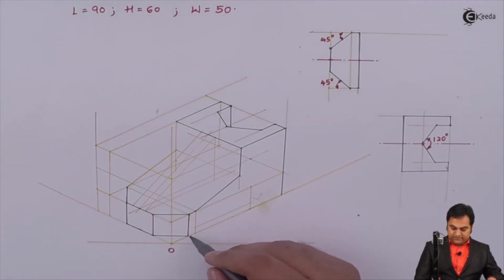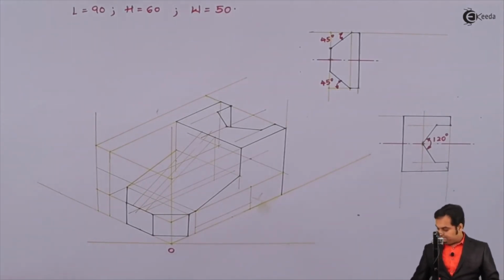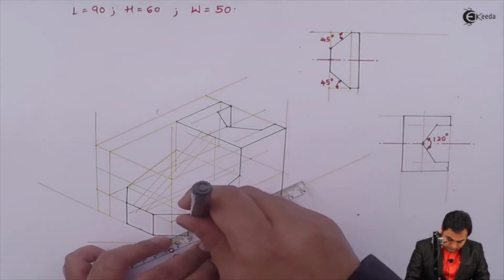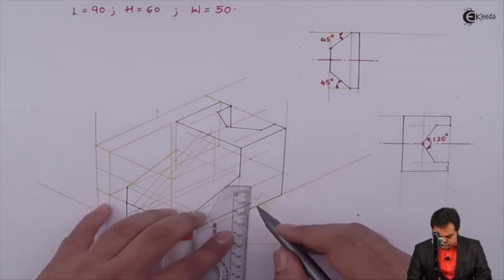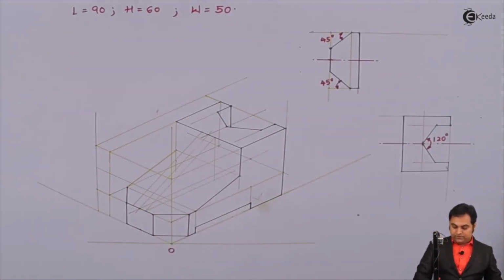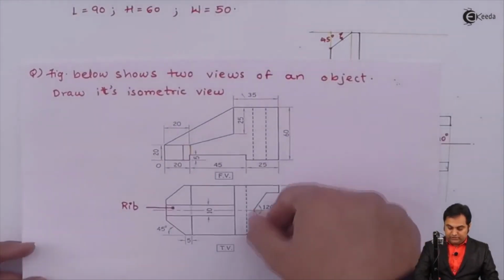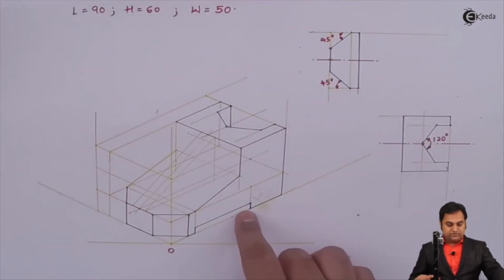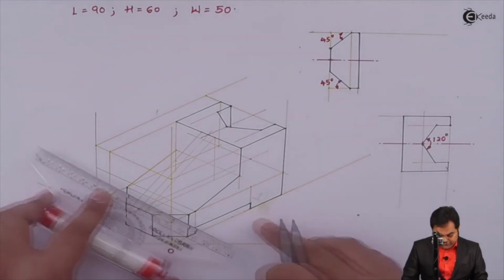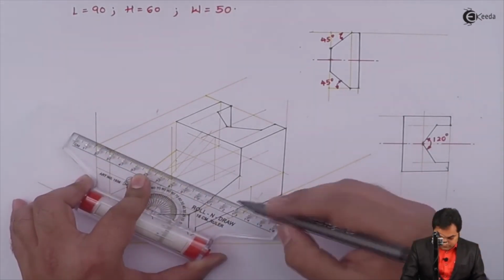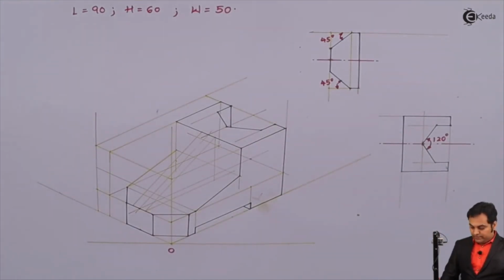Then here this plate is of 5 mm length, 5 mm height, and then this surface will be there throughout, as can be seen by this dotted line in the top view that indicates that this surface is throughout the width. For that, I'll have to draw a line parallel to the width through this point. It is throughout. Next, after this, here I'll connect this rib.